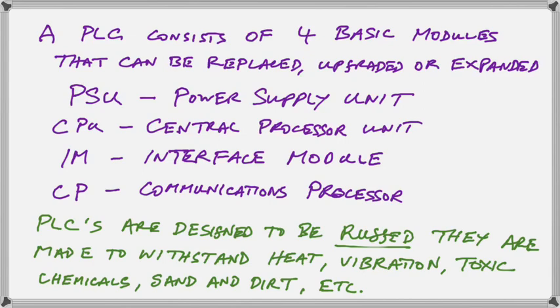Then it is associated with a communications processor. Remember that I told you that the PLC is used in conjunction with a bigger system where commands are going to be sent to it from a central system through the network, and also you will want to read those inputs at a remote location.